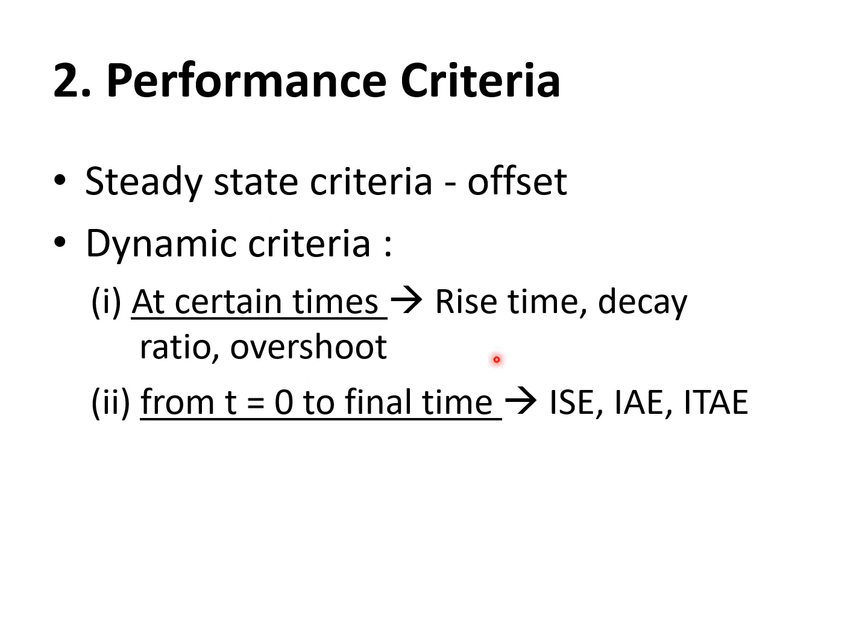A controller may give a good result in certain criteria, but not so good in others. It may not give an offset, but it may have a very high rise time, and so on. Those are the things we have to balance. There's no one method that will give the best for all. Sometimes this one gives good, sometimes this one gives not so good. You have to make your own decision on how you want the response to be.